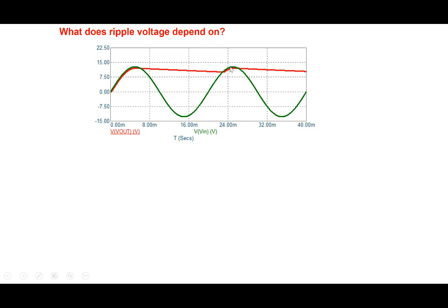For example, if this DC voltage is used to power an amplifier, the ripple can get into the amplifier and get amplified, and therefore one would have an unwanted frequency component, which can be a big nuisance and something that we really don't want.